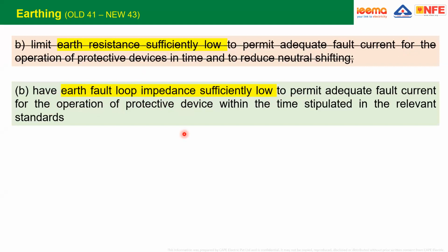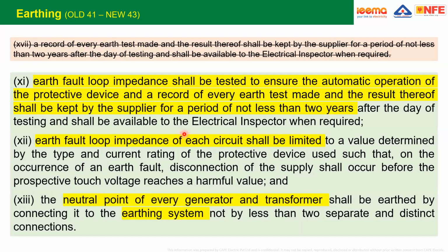Please note that this is not a new requirement. This has been included in the older versions of NEC and IS 732 as well, but we were not practicing it. But now, very specifically, it is included in the regulation. That means the electrical inspectorate also will start asking for this test report in future.